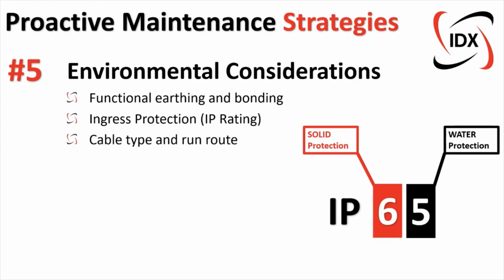What's also important is using the appropriate cable for the application. So if you have a cable running out in the field that is exposed to the sun, you need to have a UV protection cable. Bringing a cable under the ground between substations needs to be armored. And then obviously cables running around very hot areas such as furnaces should have the necessary fire and heat protection, but more likely you'll probably be using fiber optics in that case.